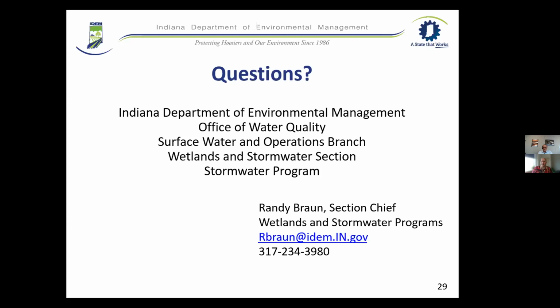Actually, you still should wait 72 hours before you grab your sample. You need to wait 72 hours for an event that would discharge through your outfall, because you don't want any kind of rainfall event to basically clean the pavement. And if you take it within 24 hours of two qualifying rain events, you potentially would affect the quality of that sample. So you should wait 72 hours. Okay.